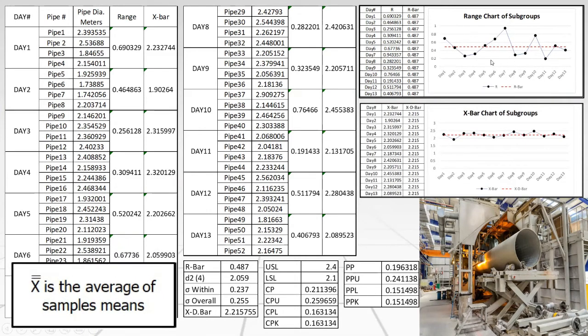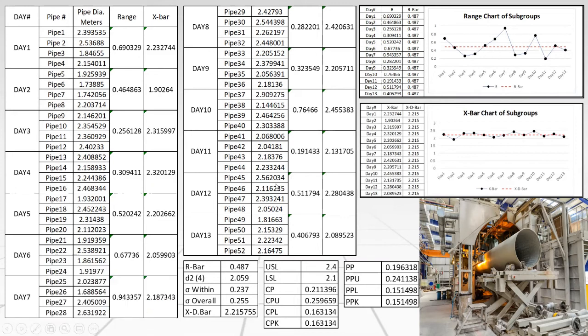Now, if we look at the range chart where we collected the 13 samples, we can see that there are high variations between the samples in the ranges, which gives us an impression that there is an assignable cause that led to these variations. And it is a must that we stop the machine and see what is the problem leading to those variations.